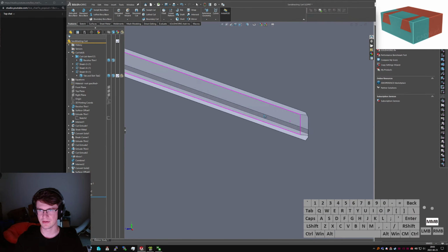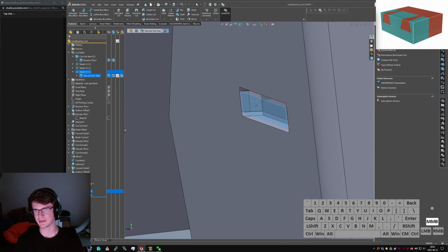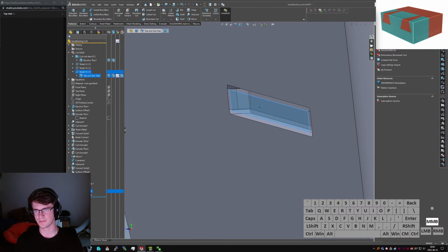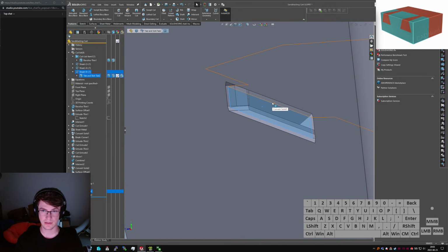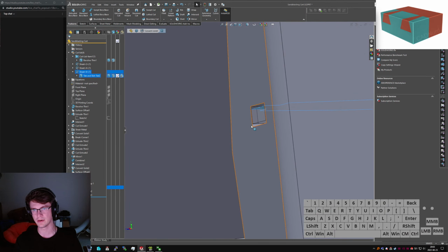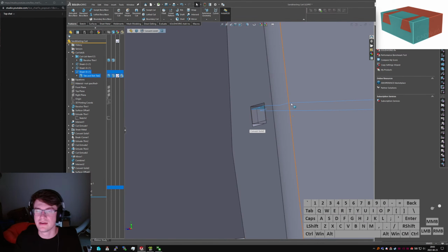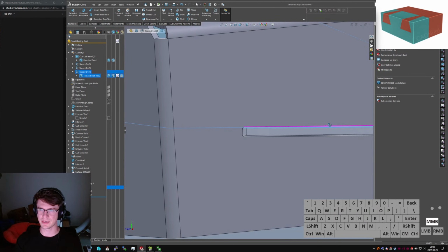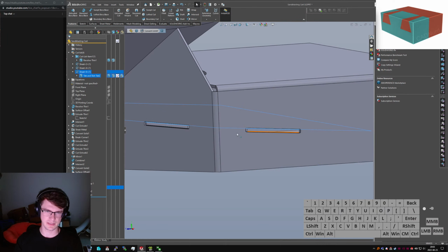I mean, it also does some nasty stuff, like these are not perpendicular to the top face. So when you exported that for cutting, you'd end up with like a little bit of bump out here. If it's sheet metal and you're welding it, it's going to be fine. But it's just one thing to take note of because it can sometimes cause some funkiness.